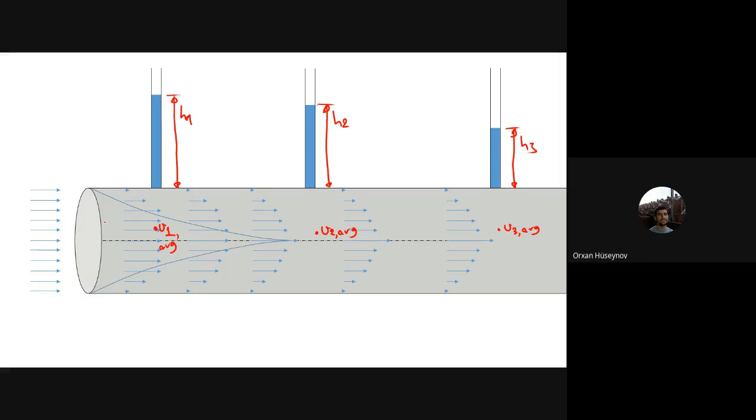If it is air, for example, you can have different velocities here, because when the velocity changes for air, that velocity change is accompanied by the density change. You will have ρ1, ρ2, and ρ3, and ρ1 will be different than ρ2, and ρ2 different than ρ3, because density change affects velocity change. But for water instead of air, the densities cannot change. Densities should be the same. Therefore, the velocities are the same for water.